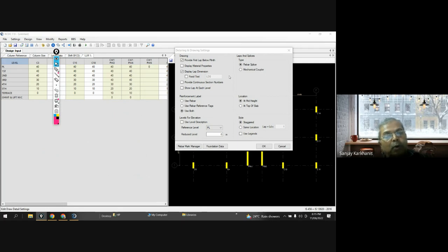If you go for lapping, there will be 50 bars of 25 dia, and that section might get congested, and the costing of the lap is more. You need 1.5 meter or at least 1 meter development length.